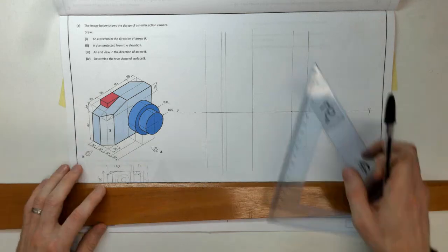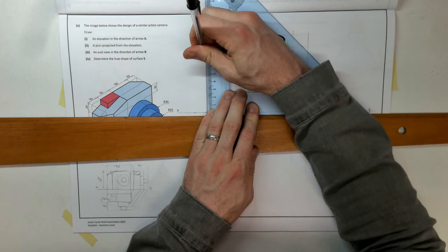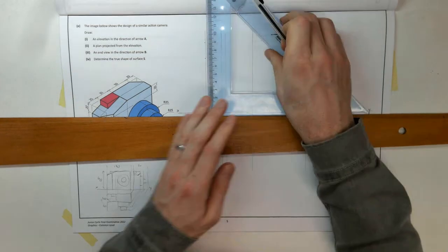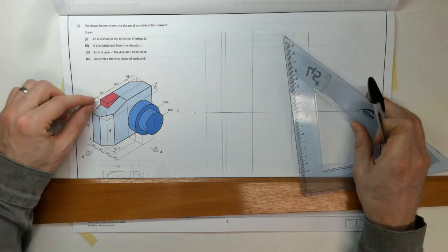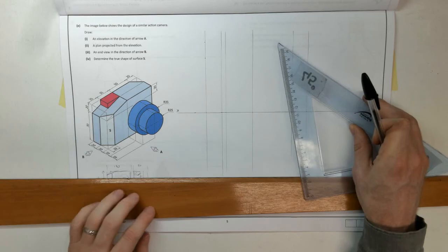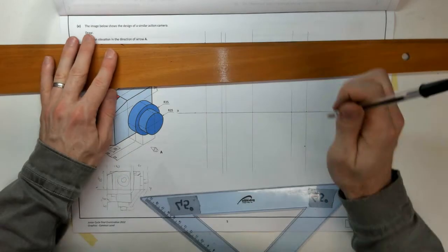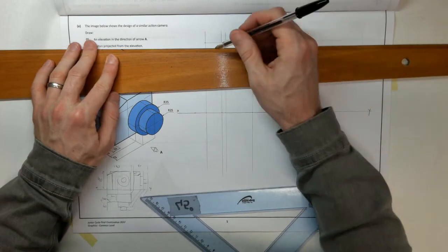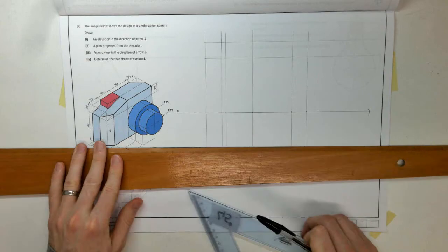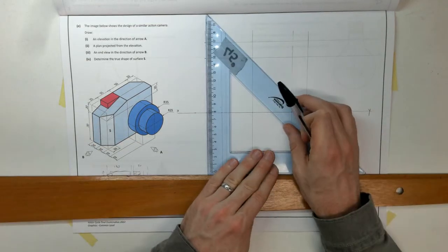Okay, overall heights then, let's step off my 70. And there's another 20, and the other heights that I need. I don't have a height for that, I'll find that in a while. We're going to have a height obviously for the center there, 20. Okay, so draw those across, and I'm just going to project them across because I'll need those similar heights for my elevation, because elevations share heights. So I'm going to draw what I can now of the front elevation.